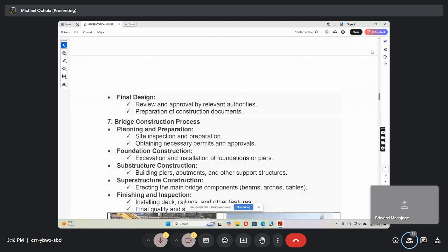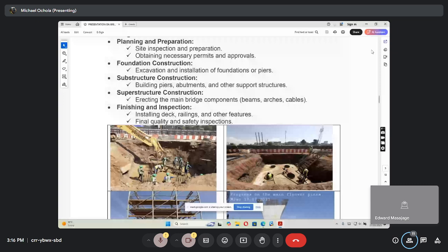You can even jump down and have a look at this excavation. I'm giving you two examples. This is a Kampala flyover. Those pier support systems you see had four piles. These piles are steel screwed piles with the concrete pile cap, and then you have the pier support. You're going to see it, so now you see the excavation and installation.